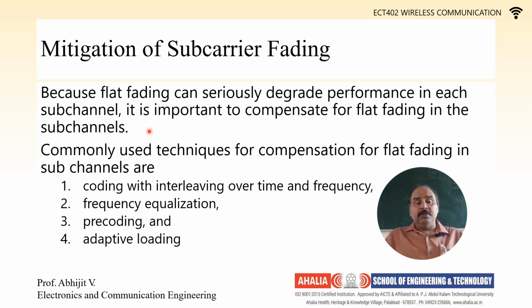This is a very important question. Because flat fading can seriously degrade performance in each subchannel, we are making all the subchannels flat fading channels, where we reduce the input signal bandwidth in such a way that it is much less than the coherence bandwidth, so that all these signals experience flat fading conditions. In frequency selective fading, the coherence bandwidth is less than the input bandwidth.